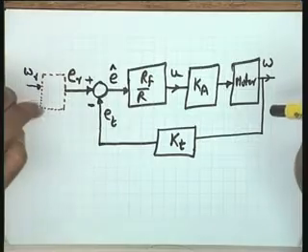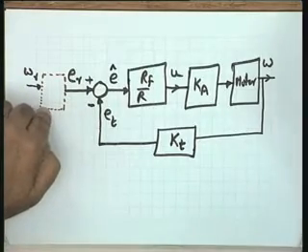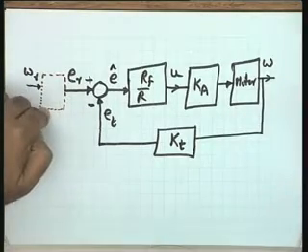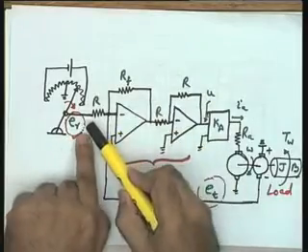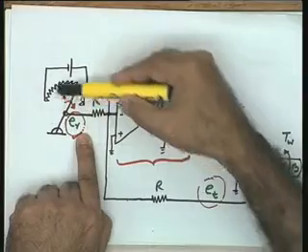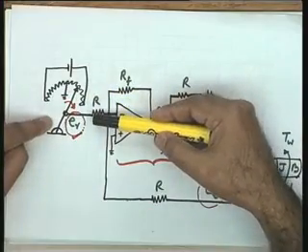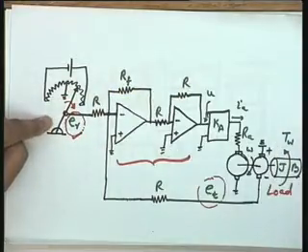You see, you can set the potentiometer constant. You know the potentiometer constant is, what is the potentiometer constant? The potentiometer voltage is equal to a constant Kp into the setting of the wiper arm. So, that is a potentiometer constant.